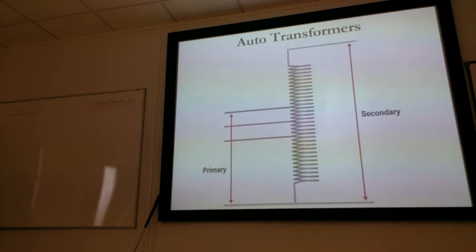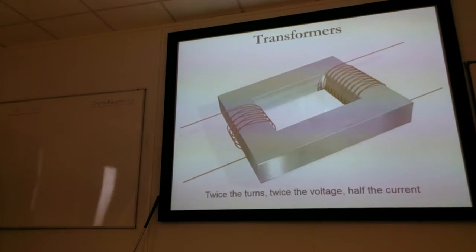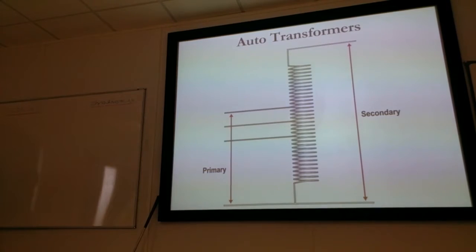We can also have a thing called an auto transformer, where, as you can see here, if you've got a voltage here, you can take off 1, 2, 3 different voltages just by coming off a different point of the coil. They're fairly lightweight, so they're only useful for lighting or low current applications. Heavy current applications, you need a chunky old transformer like that. Lightweight ones, auto transformers.